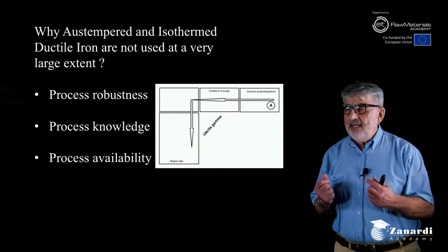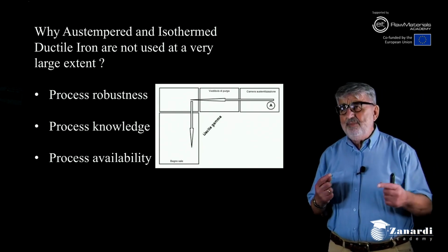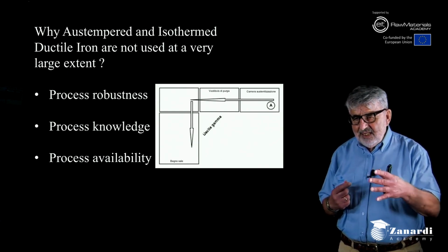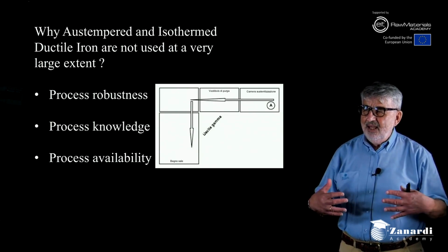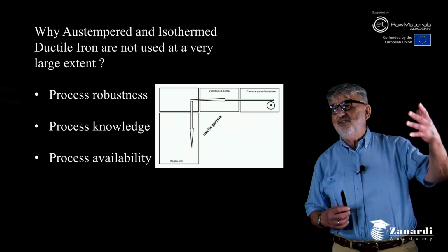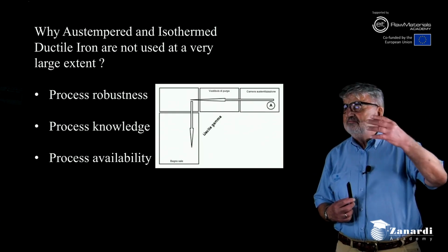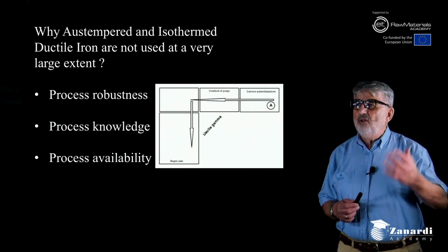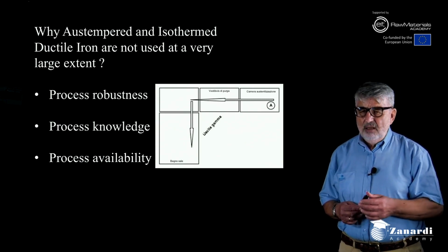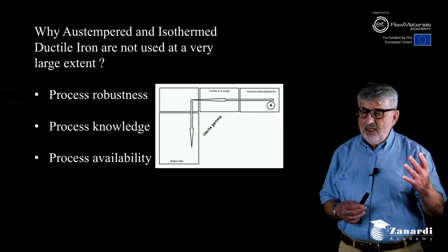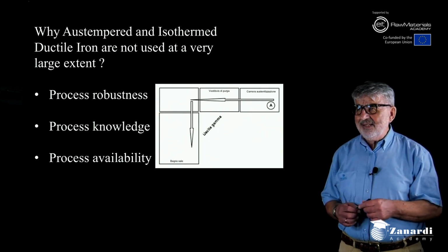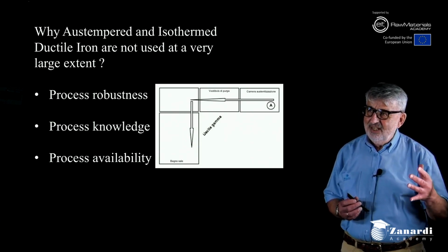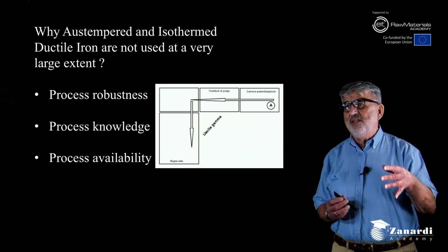And the austempering temperature that is selected for the hardness or the grade needs to be connected with the austenitizing temperature, which cannot be chosen freely depending on economic conditions, but has to be chosen in order to guarantee the maximum rate of the ausferritic reaction. That is the condition to get stable austenite.